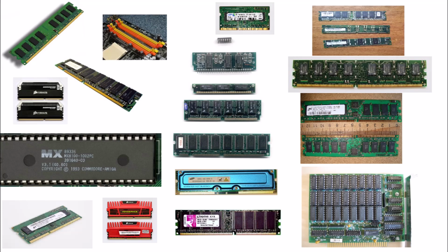There are 168 pins in the SDR/SDRAM. SDR/SDRAM is clocked at 66, 100, and 133 MHz. Modules of 16, 32, 64, 128, 256 and 512 MB were produced. Production was discontinued due to the emergence of DDR, faster and more efficient memory.